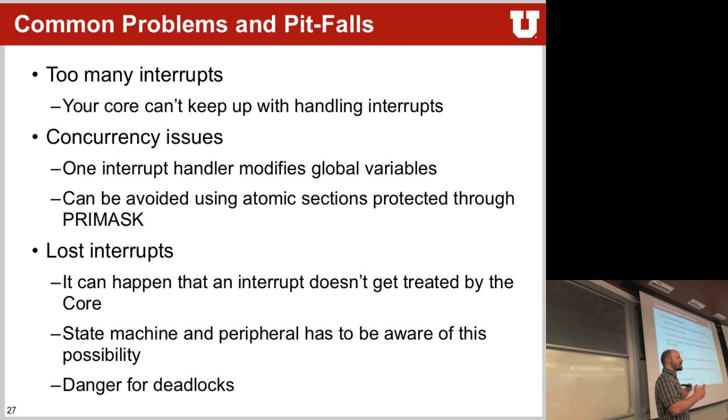Yes, so if you make a state machine, don't always assume an interrupt will come in. It can happen that you lose them. Sometimes they are just a glitch on the line and don't get asserted properly, or sometimes somebody else reads a register and clears an interrupt pending status. So for example, if you have an interrupt service routine and you have a bug and you actually overwrite the whole register and clear it out, everybody else's interrupts will be ignored and your state machine might deadlock itself. So you have to be aware of this possibility that interrupts don't always have to happen. Usually it shouldn't, but it can.